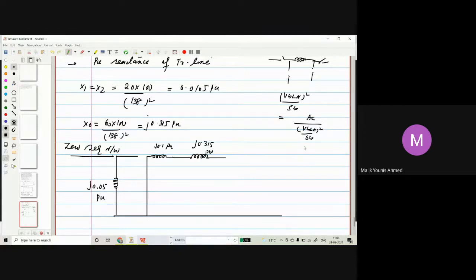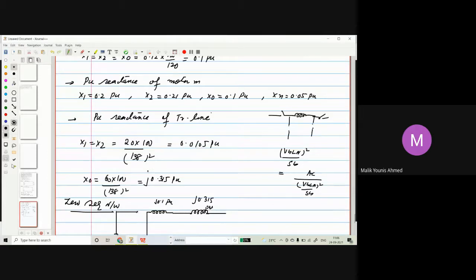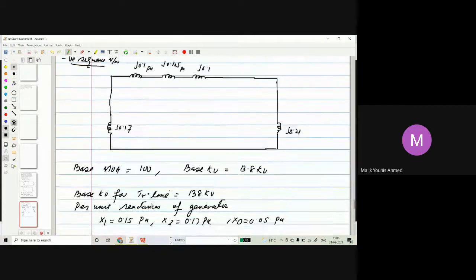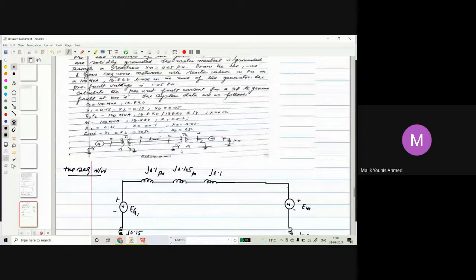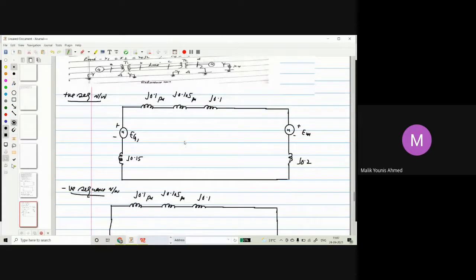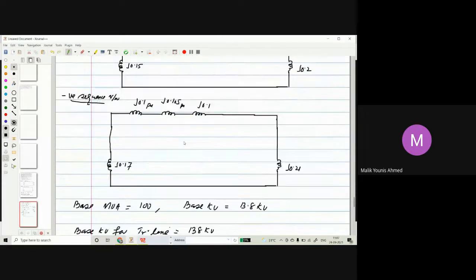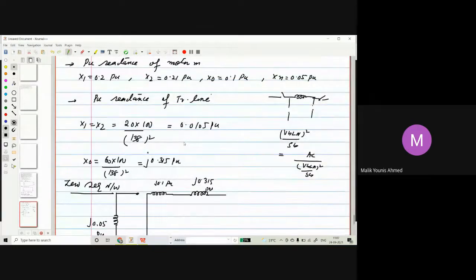Okay, next is again a transformer. So this is open here. Again a transformer, so the series switch will be closed and the shunt switch will be opened, because the primary winding is star connected, neutral grounded. I will draw the series switch closed, and now I am drawing T2.